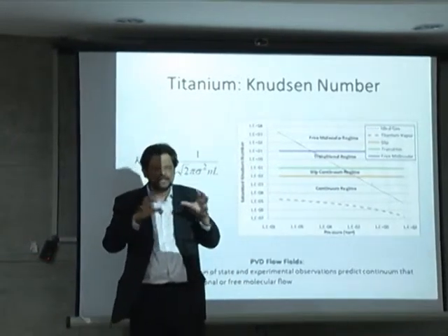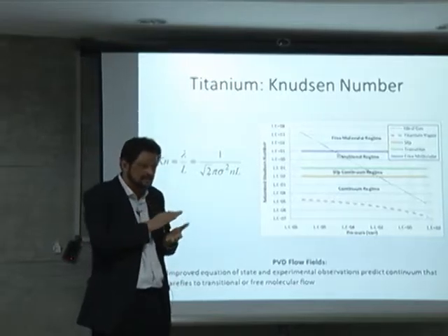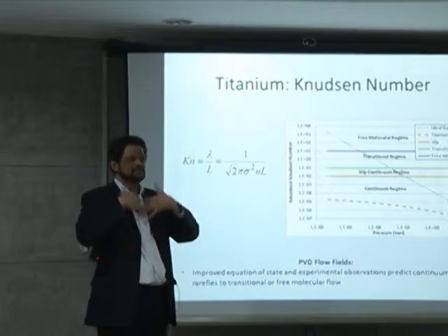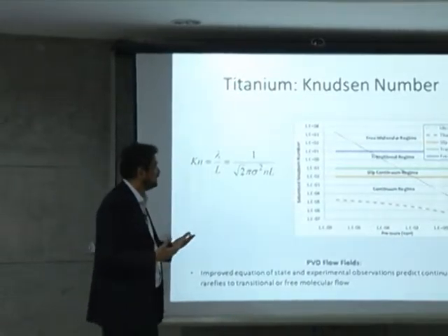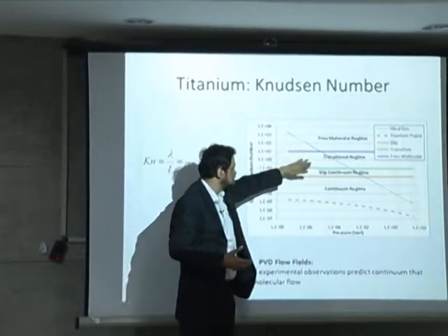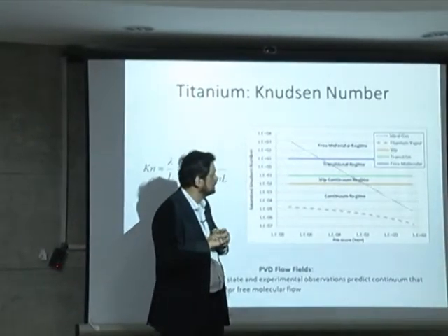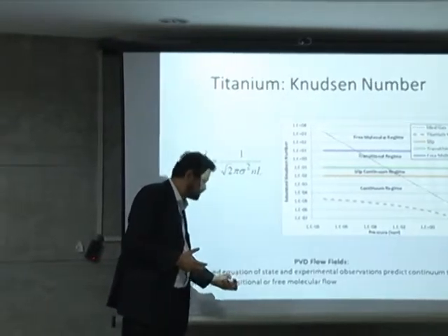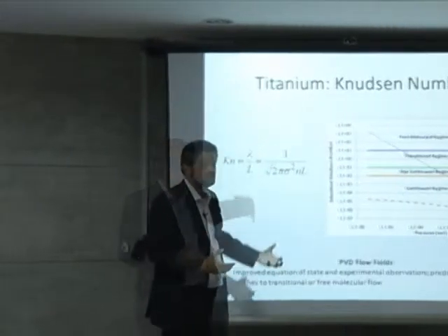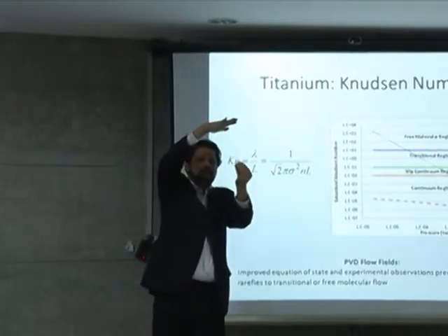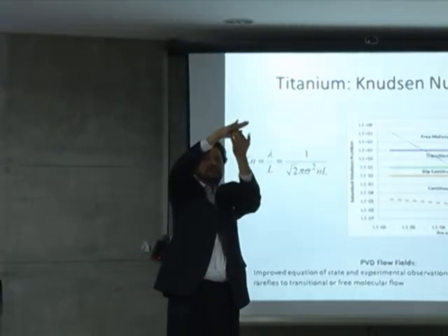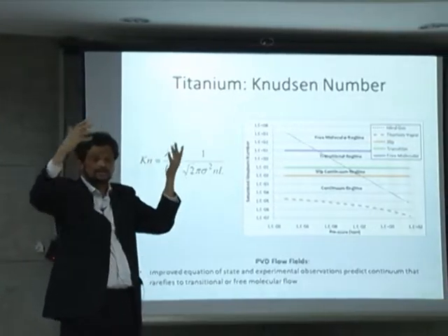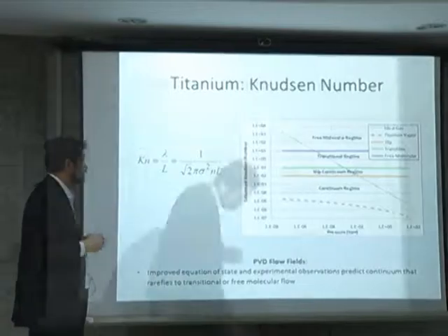So when it is rarefied, in a low density region, there is some speed that can occur even at the solid boundary, which is another complication. And then of course, when it is transitional, it becomes very complicated, in the sense that when a molecule of this material hits the substrate, usually it will get deposited. It won't even get reflected, but sometimes it may. So we had to somehow model the whole thing.